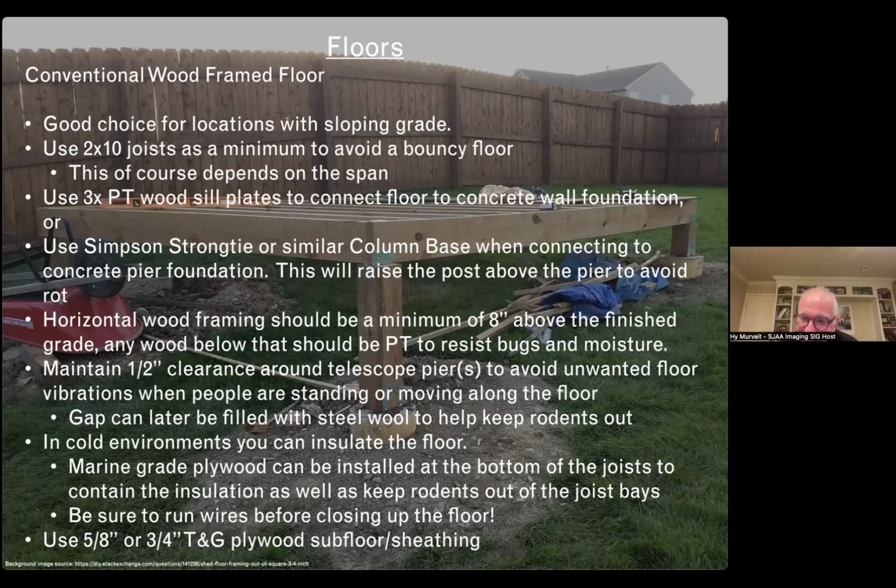It depends on the soil too. It really depends on the soil. If you have really good soil or you're on bedrock or something, you can get away with smaller. But if you're on something more silty, you're going to need a larger foundation because the soil can only bear so much weight, so you have to spread that around.